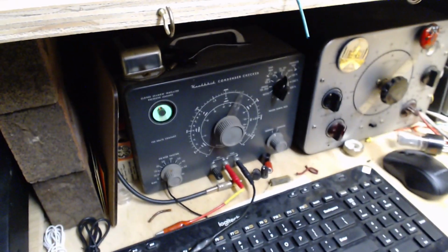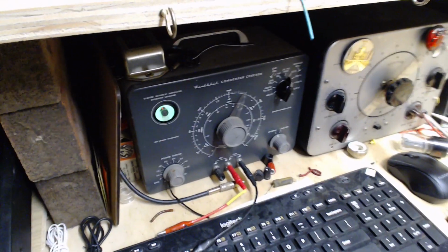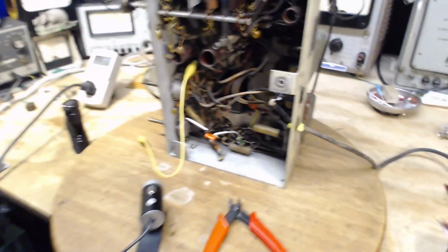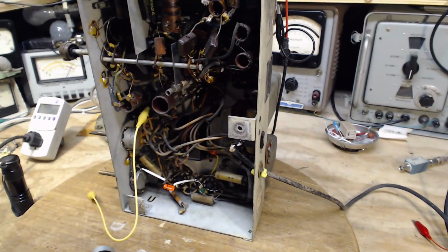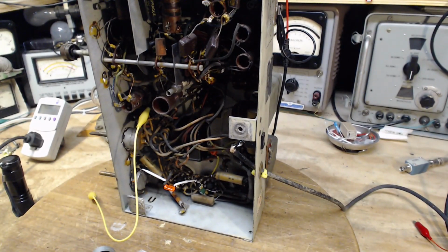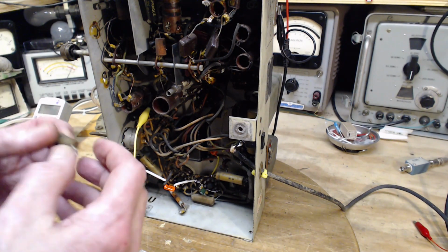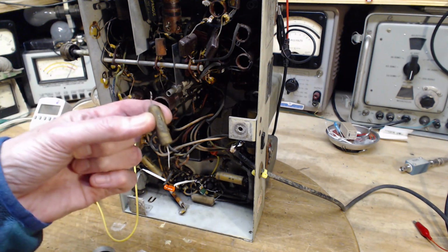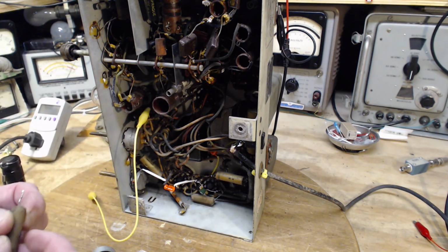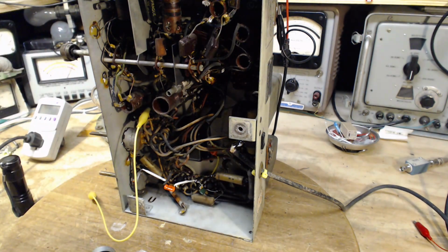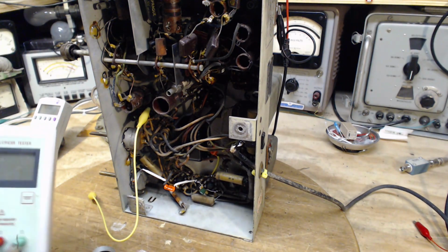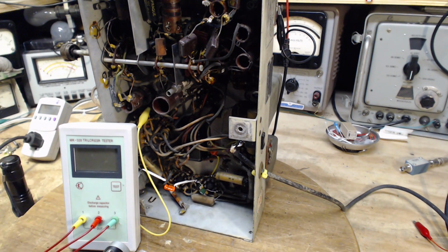Now it's on a plate circuit. There's a lot of power there. A little bit leaking through this capacitor. I can't imagine it would disturb the radio at all. What would disturb it though is a lack of capacity. If there's no capacity in here, which is highly unlikely, how could that be the case? We're going to measure it with this instrument here, but because we know it's leaky, the measurement will be false. But let's do it anyway.